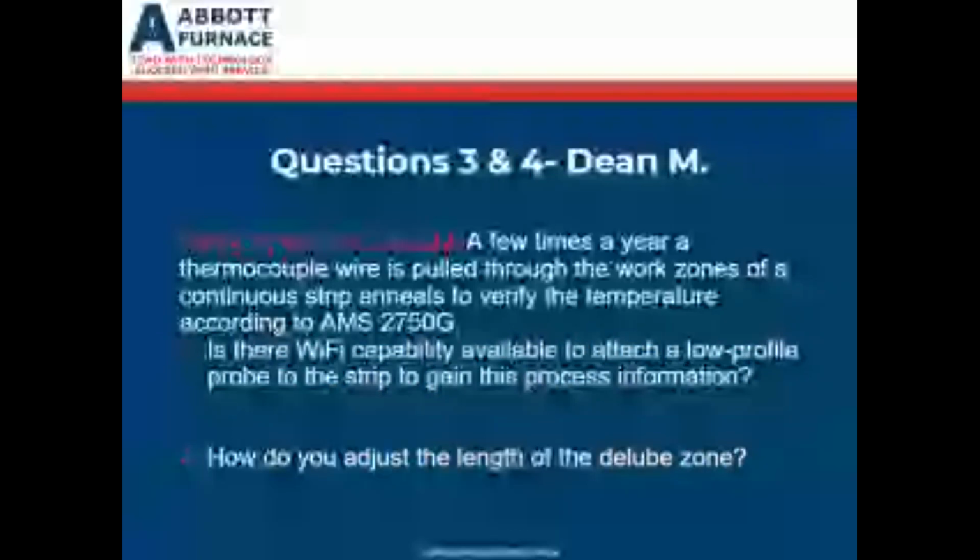So unfortunately, there is nothing that you can just simply set on the belt that would run through and record it, unless you're doing something under like 1,200 degrees. I believe they make stuff for lower than that, but for a normal sintering furnace, there's nothing available at this time.